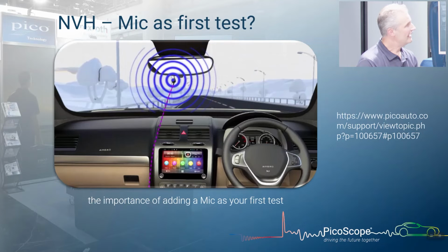And it's a good point to add here that whilst the wizard doesn't ask you to add a microphone, I'm a firm believer that adding a microphone will give you a little bit more diagnostic information. And like John mentioned there, if you've got the standard kit, then you can do this. You can have a microphone connected simultaneously. And we'll have to go back into the menu and amend slightly for a 3-axis plus single channel measurement.